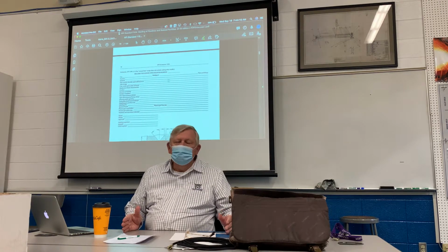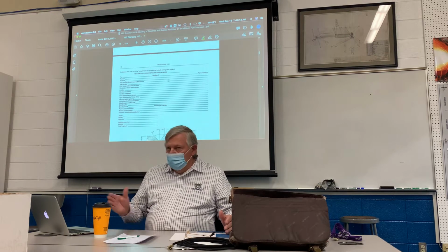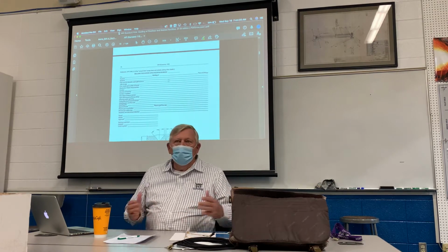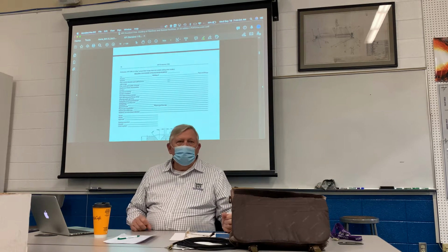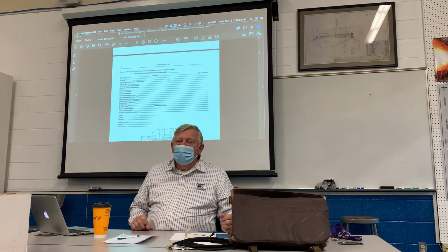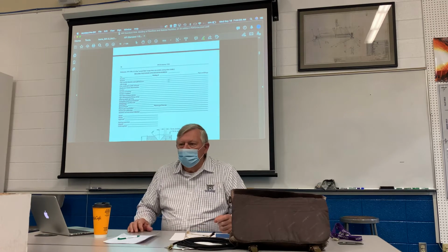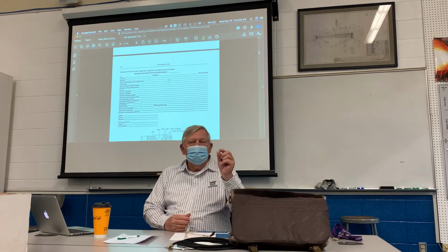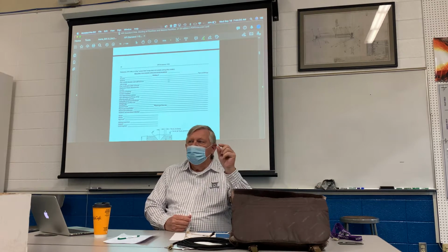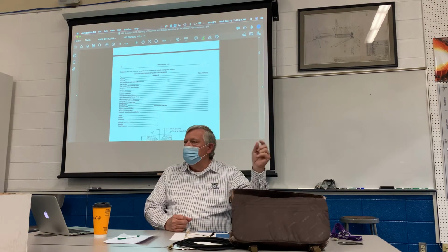ID. Over 12 is outside. Okay. Wall thicknesses. Where do you find the wall thicknesses? Might have to Google that. All you have to do is Google pipe schedule or pipe wall thicknesses, and then you have to look for the API 5L group, and it'll tell you the wall thicknesses that pipe comes in.